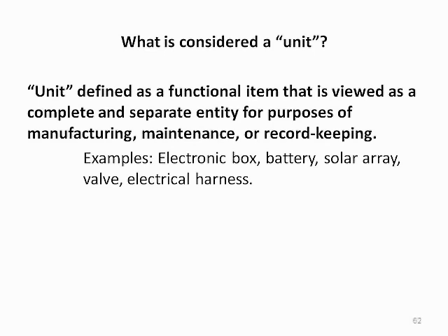We will first turn our attention to unit level testing. Unit will be defined here as a functional item that is viewed as a complete and separate entity for the purposes of manufacturing, maintenance, or record keeping. Examples include electronic boxes, batteries, solar arrays, valves, and electrical harnesses.